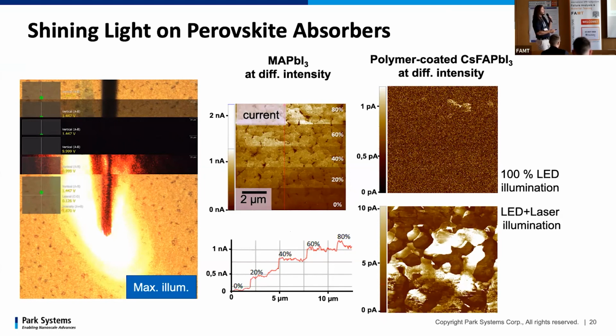Others use different absorbers not based on iodide but on bromide, which has a larger band gap and can be combined in tandem solar cells. Another option is a 2D approach, where we intentionally break the three-dimensional network using very large organic cations to create hydrophobic blocks in between, stopping the progression of water within the structure.